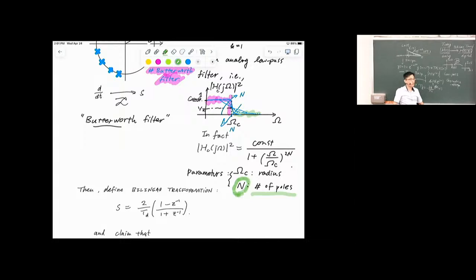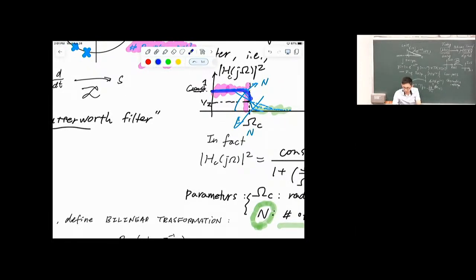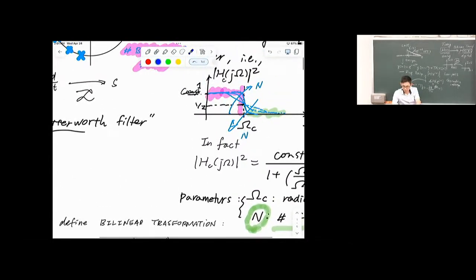The Butterworth filter: if you design your system to locate your poles right on the circle, on the left-hand side of the circle, then chances are you may be able to create a magnitude response which not only decreases monotonically, but also we can control the transition and freely select your cutoff frequency. There's a control. It's a very nice design, a classic design.